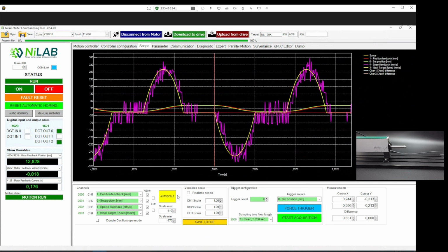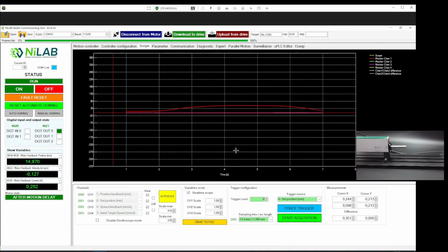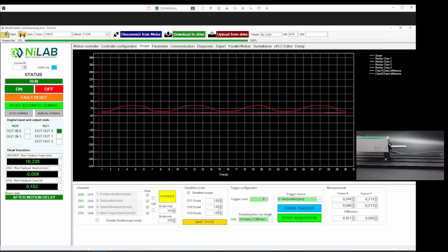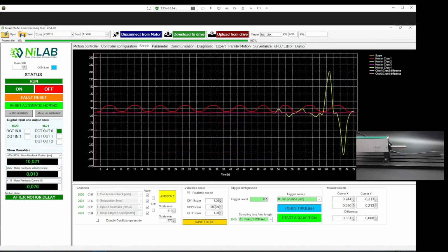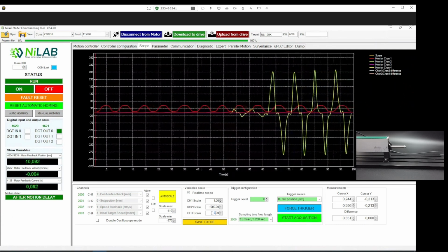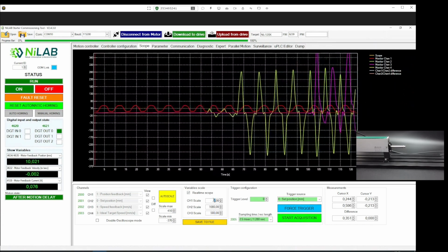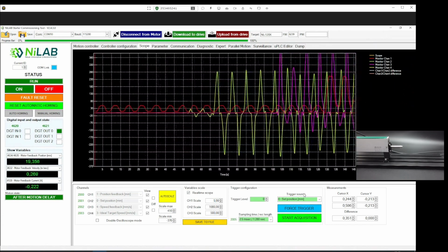Finally, the oscilloscope offers a real-time mode to monitor the variables from the status bar on the left. After enabling this function and starting the acquisition, the signals will stream live on the screen. To improve visibility, simply increase the zoom value of the individual variables, typically to 500 or 1000, to clearly see the real-time signal trends.